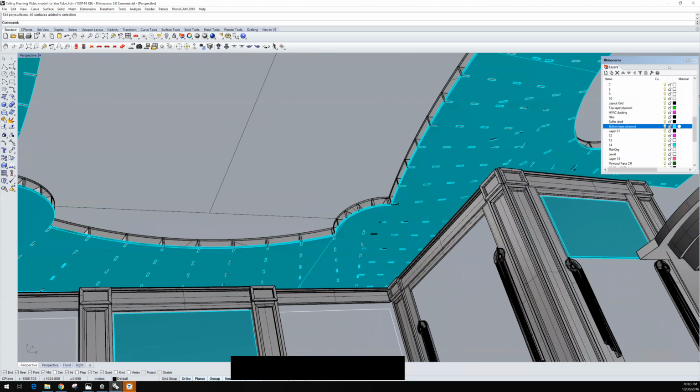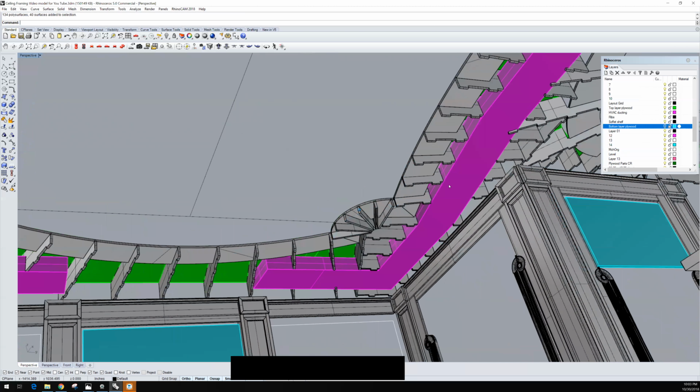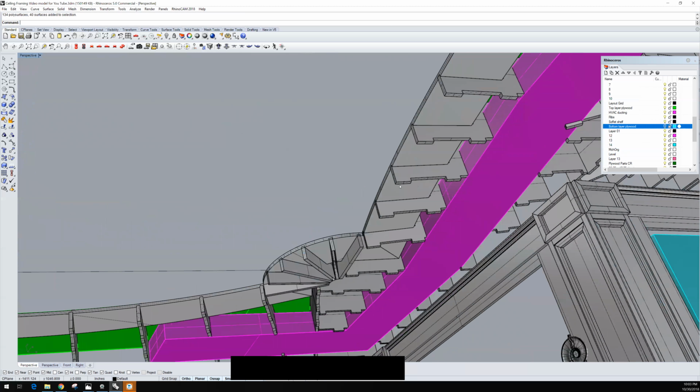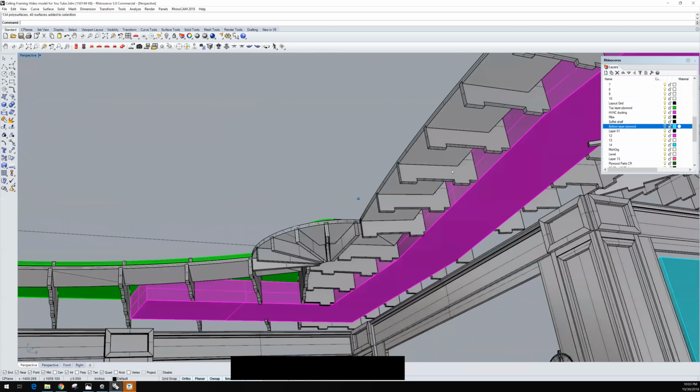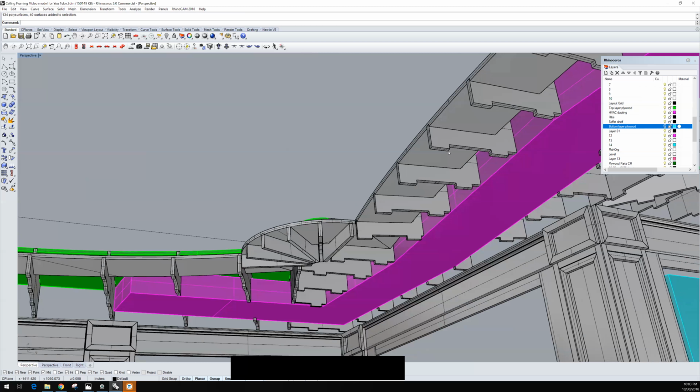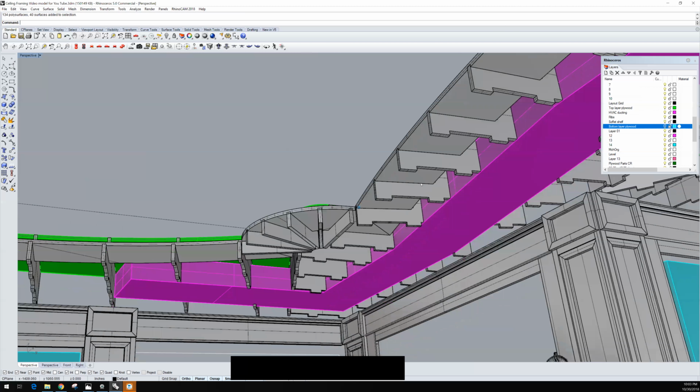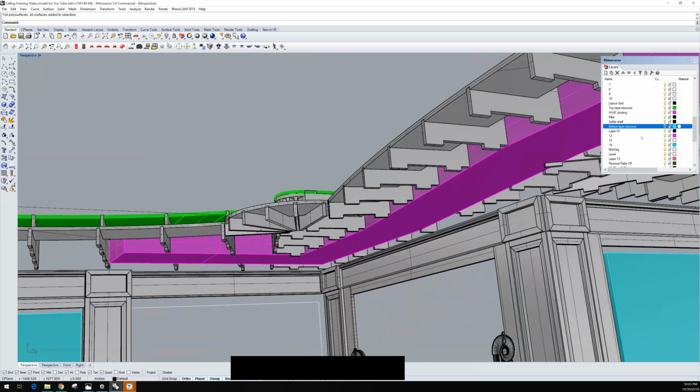So it has, just as we did on the top when we put all those rib pieces in there, you can see this little joint. I think it was 2.5 or 3 inches. I believe all this plywood spec'd out at 0.72. It was a Russian birch that we used, really good quality plywood. And we gave ourselves a 0.008 offset of the hole in the next layer of plywood, so that we weren't fighting it. But you know, with the application of glue and screws going into that bottom layer into this guy, this thing was rock solid. So let me show you that layer again.